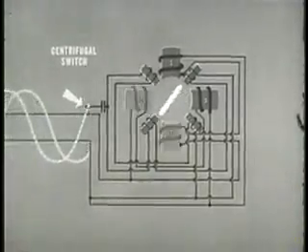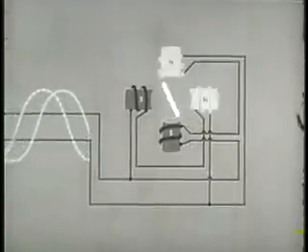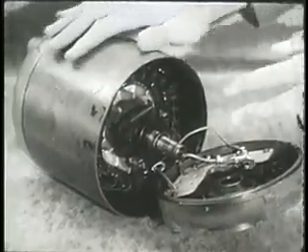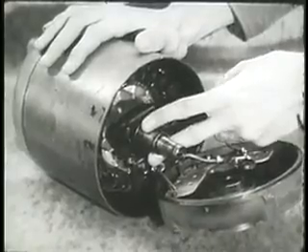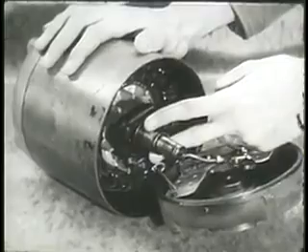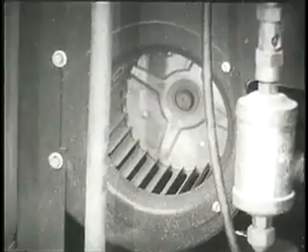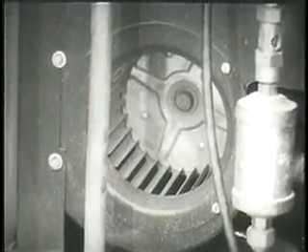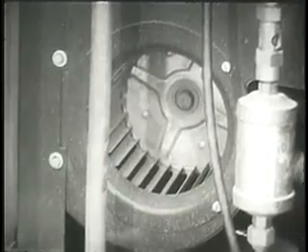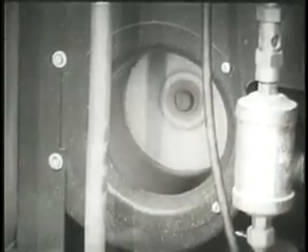When the motor has attained 25% of its running speed, the centrifugal switch disconnects the starter windings. The centrifugal switch is mounted on the rotor shaft and is the type used on most split-phase motors. Since the greatest phase shift and relative motion is caused by the capacitor start method, it is used in situations where good starting torque is an important consideration.